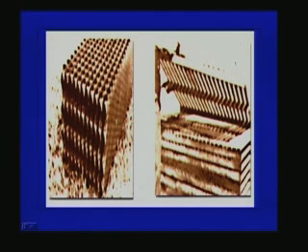And this figure shows the typically used synthetic media which is serving as the support media. So here you can see that it is a synthetic media, it has a lot of surface area for the growth of the microorganism. You can see here all the pores running throughout the media. So the porosity of this medium will be around 90 to 95% of the total volume, and the specific surface area is around 200 meter squared per meter cube. So you can imagine how much biomass this type of supporting media can hold.